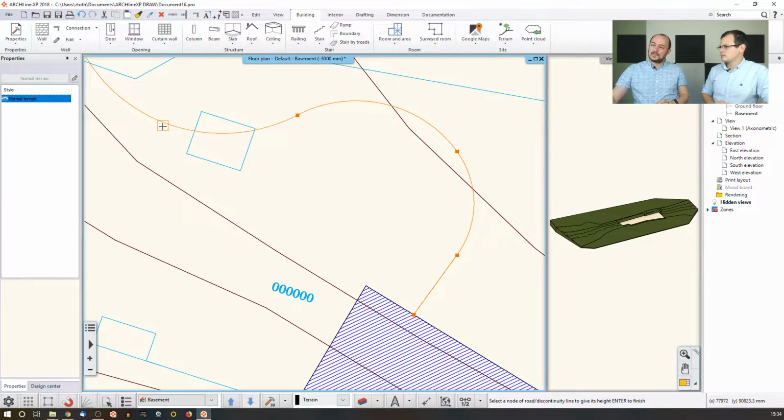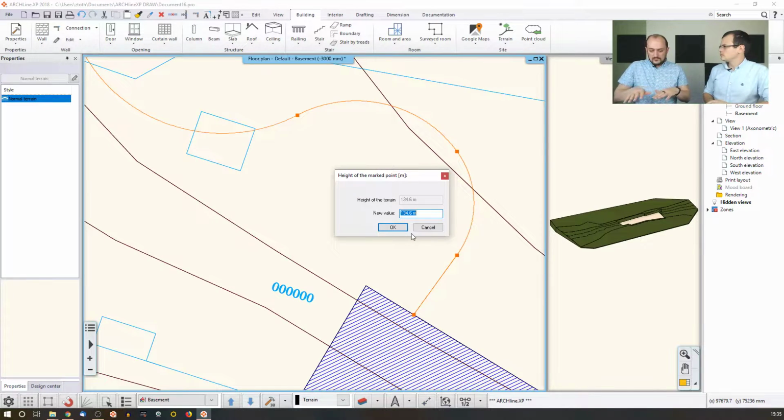So now the software, assuming that it's starting from this specific point, set up this specific height for this road, and if you do not change it, it will just continue going on this same height. But in this case, because the terrain is having this specific slope, it will need too much of the terrain to extend itself. So I will just go with this one. That's fine.